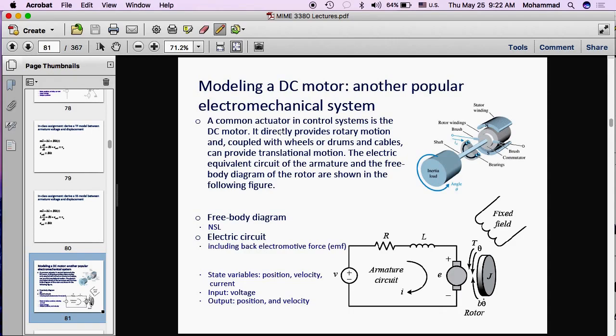And unfortunately, this is not a perpetual motion machine. So that voltage is actually opposing the voltage that you apply to get the whole thing to move. So the point is, whenever you have a wire winding that rotates in a magnetic field because you have applied a voltage, there would be a secondary voltage generated that is unwanted. It's like friction, but it's in an electrical type friction. So you create an opposing force, which is an opposing voltage in this case. So we are going to take that also into account.